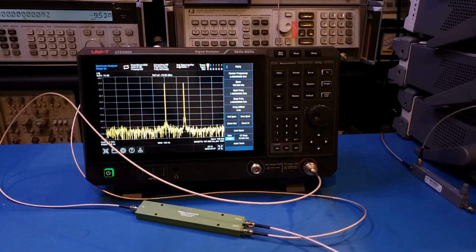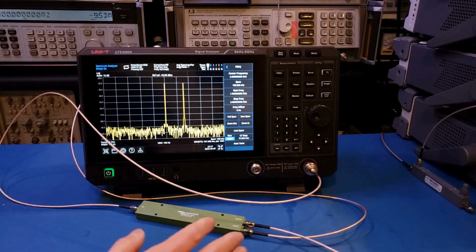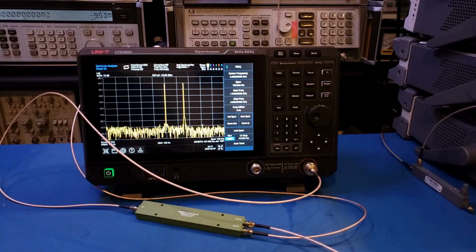All right, here's the setup. I have 2 signal generators. One is my HP8642B and the other is my HP8671A. Both of these generators are set to output 2 GHz. Because they're running with independent clocks, the output frequencies are ever so slightly different. The output signals are combined using this Wilkinson combiner, and the output from the 8642B, you can see here, currently is set at roughly minus 9.5 dBm.